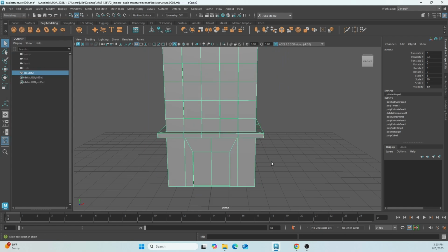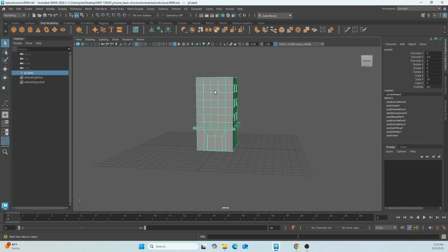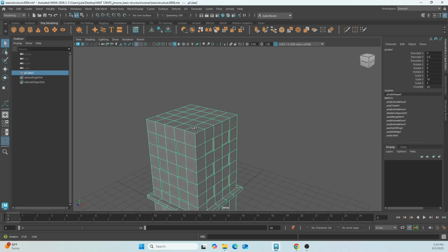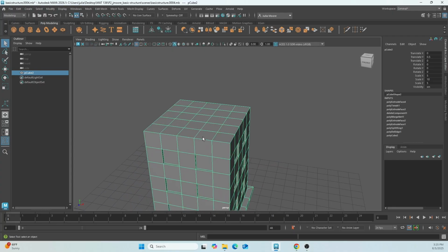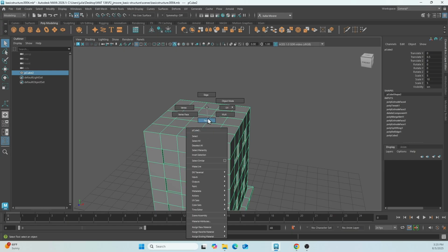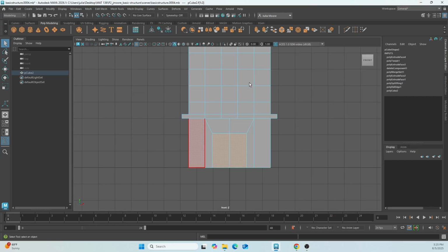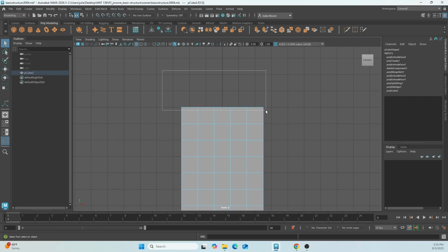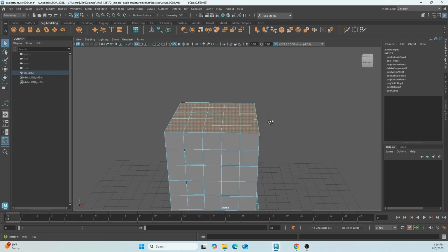Increment and save. Okay, so we have our awning, we have our windows, and we have our little door. Let's add a roof. Now with the roof, we're going to make about 3 extrusions in total. So I'm going to select these faces on top by going to front mode and drag selecting everything on top, holding Control and deselecting these ones right here. So that means that just these ones on top will be selected.